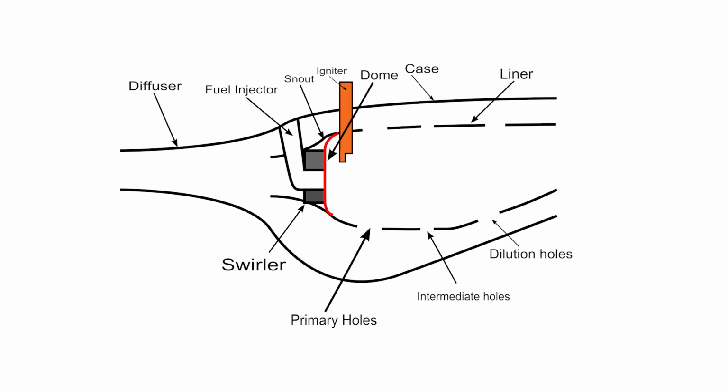Next is the diffuser. The purpose of the diffuser is to slow the high-speed, highly compressed air from the compressor to a velocity optimal for the combustor. Reducing the velocity results in an unavoidable loss in total pressure, so one of the design challenges is to limit the loss of pressure as much as possible. Furthermore, the diffuser must be designed to limit the flow distortion as much as possible by avoiding flow effects like boundary layer separation. Like most other gas turbine engine components, the diffuser is designed to be as short and light as possible.